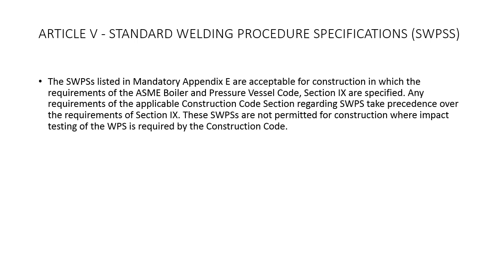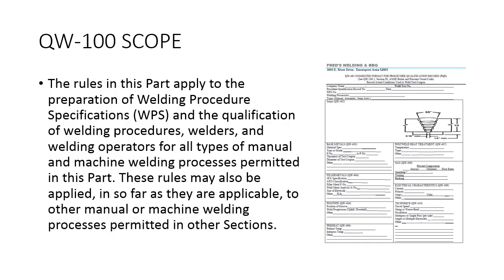But if you got to do impact testing, let's say you're doing some kind of cryogenic situation, liquid nitrogen or liquid natural gas, you can't use these. If the construction code requires impact testing, you can't use a standard welding procedure specification that you purchased. You'll have to qualify your own.